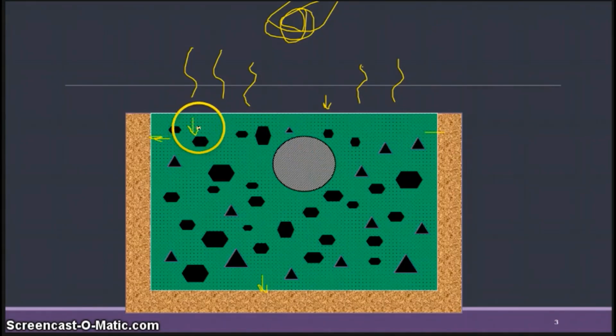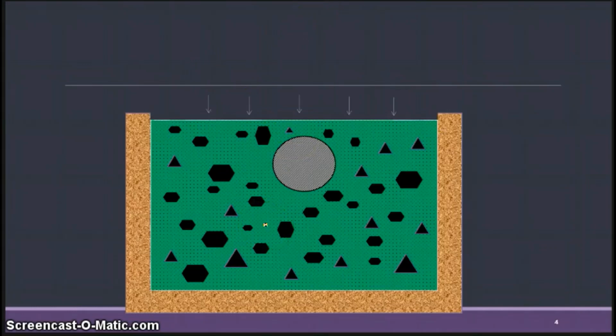When it loses water in this place, it tends to go down, because whatever volume was held by water is going to go down. Generally, because we vibrate it and finish the concrete at the top surface, we have a lot of sand, cement, and water mixture. Not much of coarse aggregate is going to be present here. So when this water is lost due to evaporation, the concrete subsides.